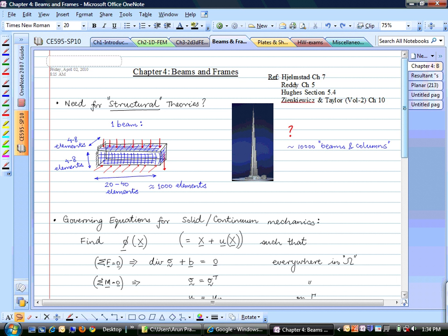But during all this analysis, you have to keep in mind that if you are using a linear material and small strain, then this is a linear model. What it really means is that if you apply a force P, you get a displacement delta and some stress sigma. Then you apply 2P, you get 2 delta and 2 sigma.